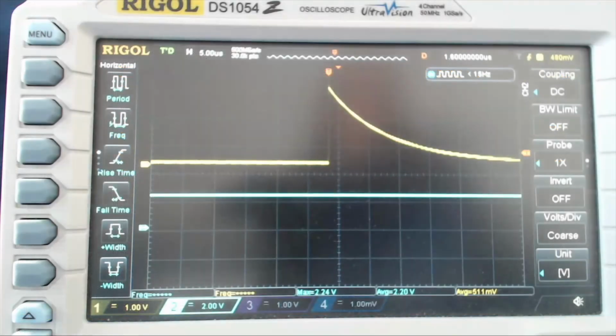As you can see on the oscilloscope, the threshold by default is set to 0 because the register is initialized to 0 at reset. So with a threshold of 0, this is well below the signal baseline. So the output signal, the digital discriminated signal, is always high.